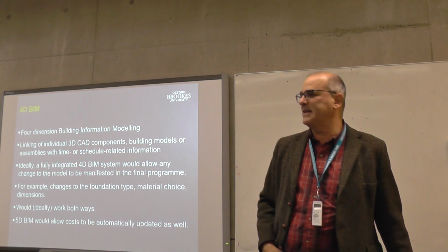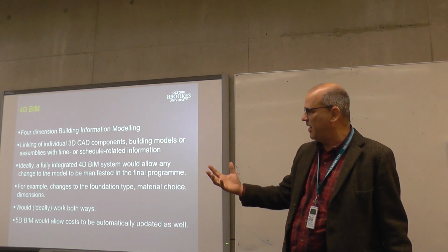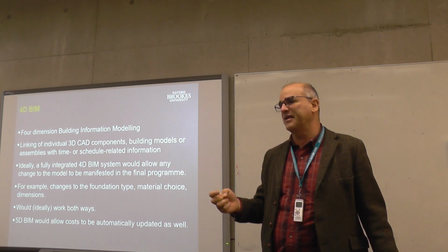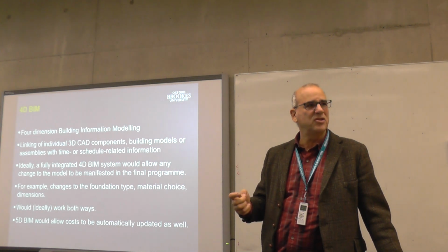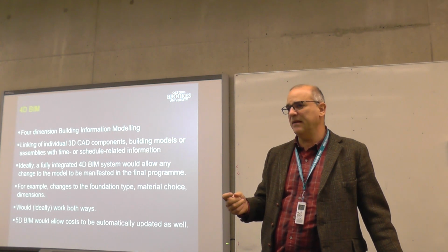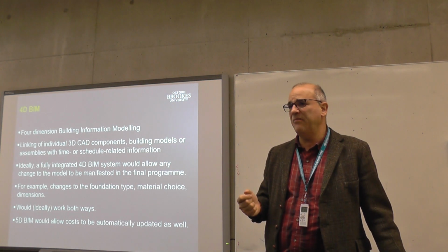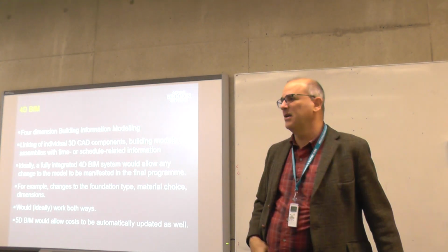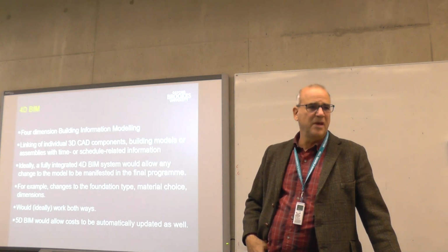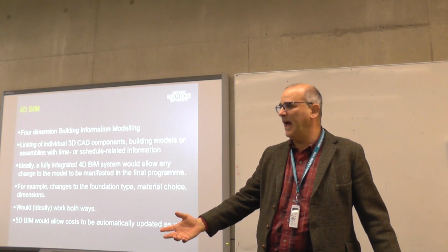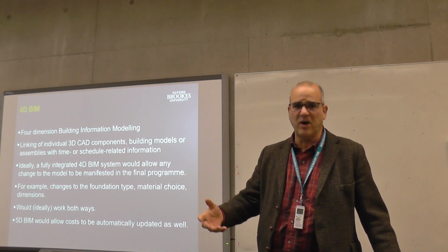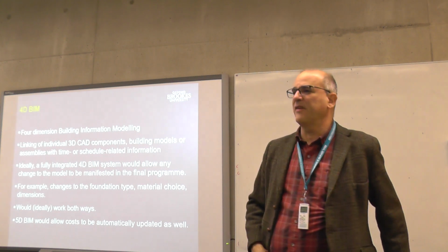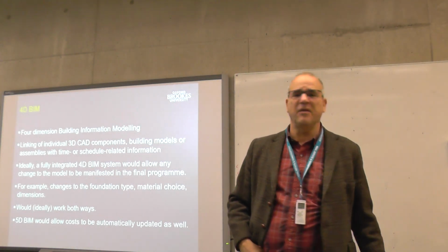So anyhow, the real idea behind the 4D BIM is that changes in the structure of the building, so you're working on a design and say you've decided to change a concrete frame to a steel frame. Seems like a fairly minor change, but actually it has a great deal of impact on the program. Concrete, you build the forms up and you pour the concrete. Steelwork you have to pre-order, it has to be custom designed and fit, it has to go through a whole series of steps. So the whole scheduling will be put off by it.